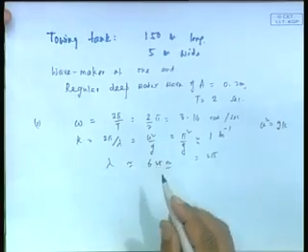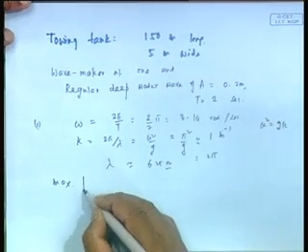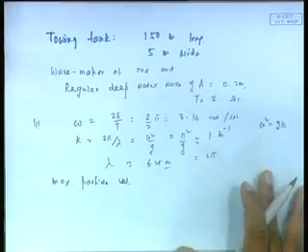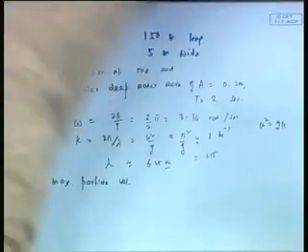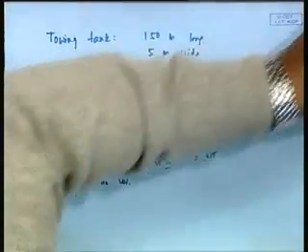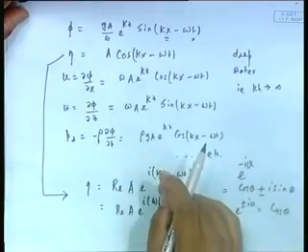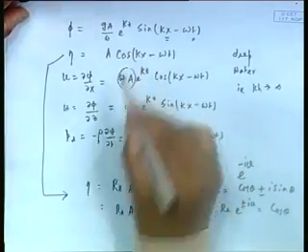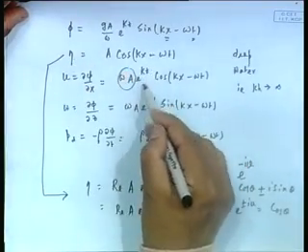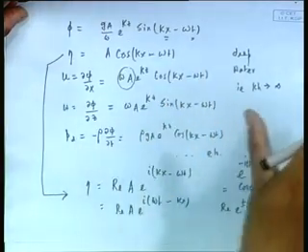Now, it says to find the maximum fluid particle velocity in the tank. Tell me this. Now, you see here we will have to go back to our expressions for u and v that we derived before. What is the maximum u? Remember that the maximum value of e to the k z is only 1, because z cannot be positive, z is 0 to negative.